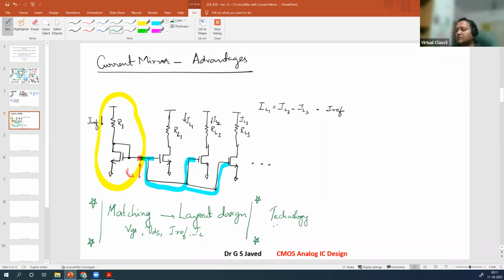As the technology scales down, the values scale down, the geometry scales down, and you will have a lot more parasitic components coming into play. It could be the resistors or it could be capacitors. So you will find that the jobs in layout design, the majority, are to ensure that this matching is maintained in most of the cases, right? Most of the cases, this is what it is. So this is one job relevant work.